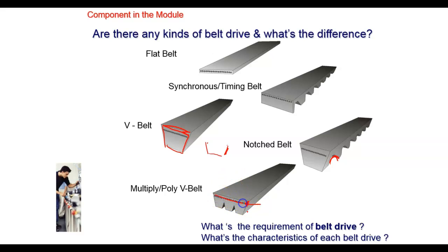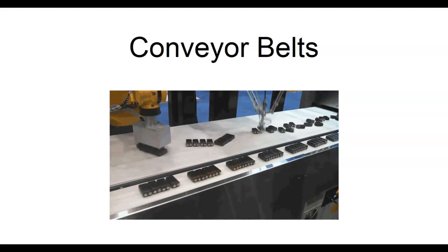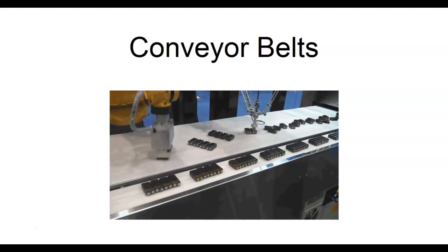Anybody ever cut a belt apart? What's that usually right there? Strings of metal, but it's going to be like Kevlar or something like that, something that's real high strength threads running in there. So that right there is your strength member. That's what's giving the belt the actual strength that it can have.